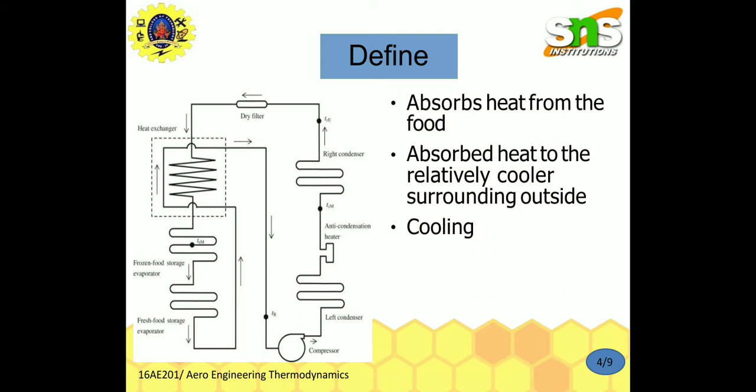In the first stage of this cycle, the refrigerant absorbs heat isothermally from a low temperature source, and then the refrigerant is isentropically compressed and its temperature rises to that of the high temperature source. Then at this high temperature, the refrigerant rejects heat isothermally. The efficiency of a refrigerator or heat pump is described by a parameter called the coefficient of performance.